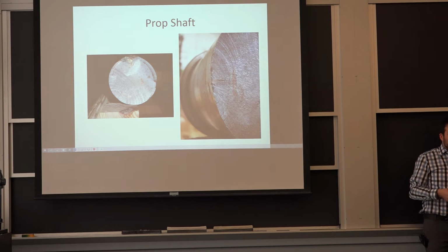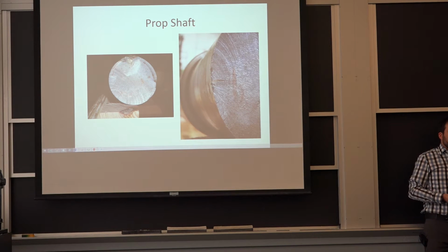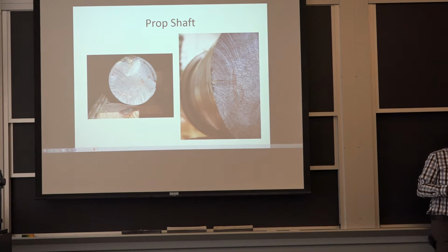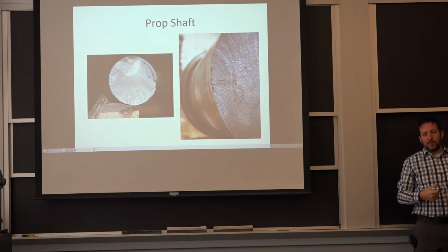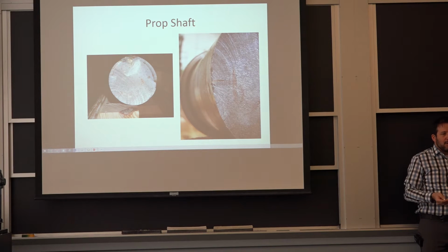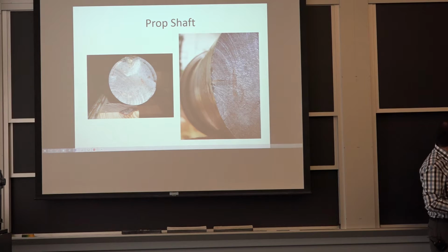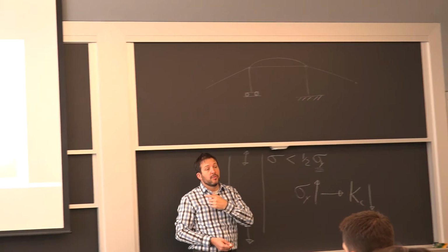So you know that the load, especially in bending, was probably only 25%. This is estimated, but it will be of the order of 25% of what it would take for that axle to actually bend permanently. So, not excessive load in terms of short-term use. So instead of being here with this half of yield strength for crack initiation, we know we were at 1/4.